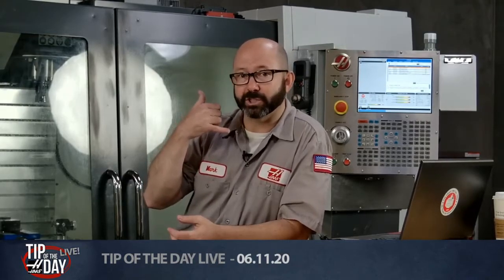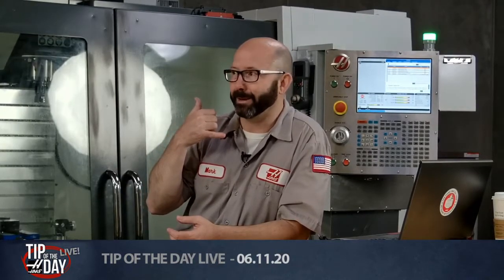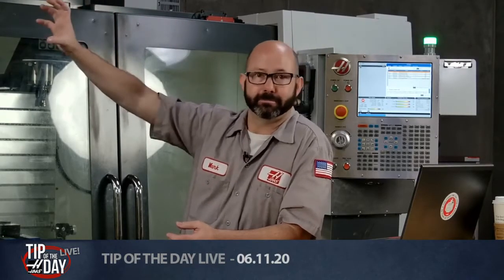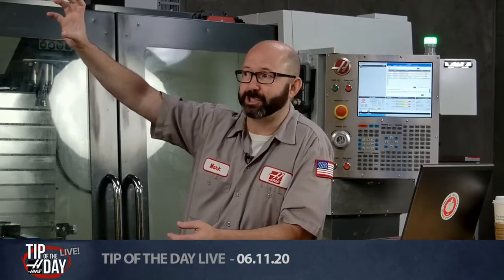So my recommendation to you is mill or lathe, do not use a G28. There's just no good reason for it. I'm sure there is a good reason for it. I've just never, the calls that I get are, hey, I just crashed my machine using a G28. Why did that happen? And so the easiest way to avoid that is stop using G28. Just go ahead and use a G53, which is a real machine home position. When you call up a G53 Z0, it's going to go where you think, right back to machine home, not some other place first and then machine home, which no one is expecting.